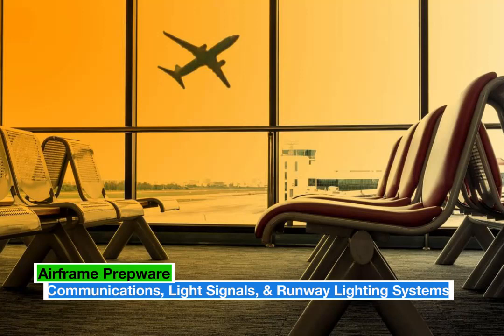Which control element of an autopilot system is an attitude indicator? Sensing. What will occur if an aircraft attitude is changed by its autopilot system in order to correct for an error and the involved control surfaces are returned to streamline by the time the aircraft has reached its correct position? Normal operation.